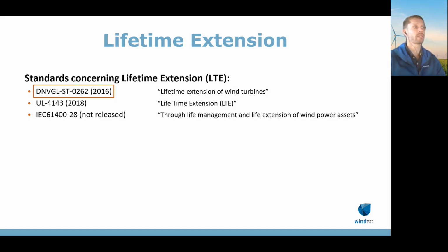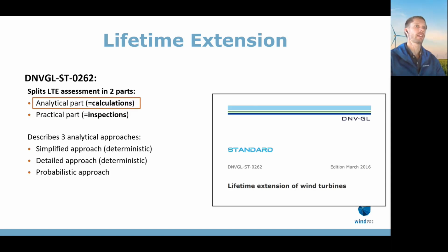We also are part of this -28 working group, and also the IEA Task 42, which are providing input for these future standards. But for now, we think that the DNV-GL standard is the go-to standard for lifetime extension. So we have aligned the calculations in load response with that, and that's what I'm going to take you through now. The DNV-GL standard splits the lifetime extension assessment in 2 parts: an analytical part, which is just calculations, and a practical part, which is inspections.